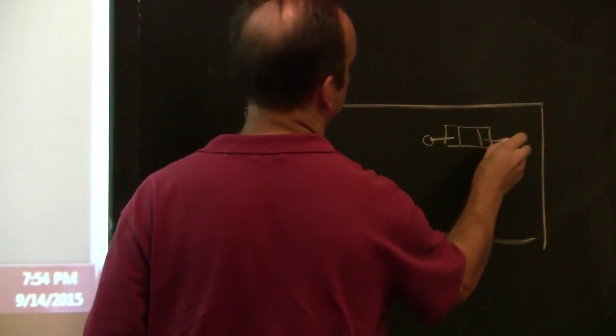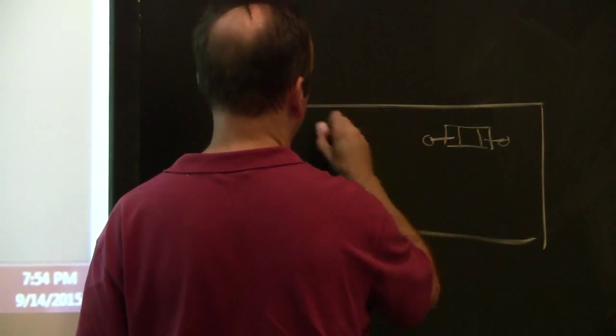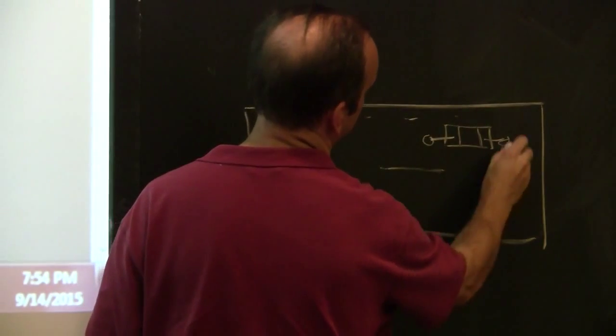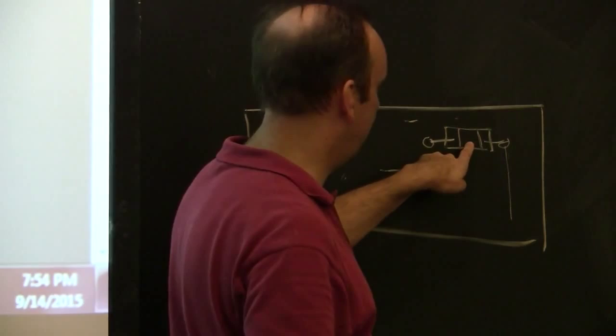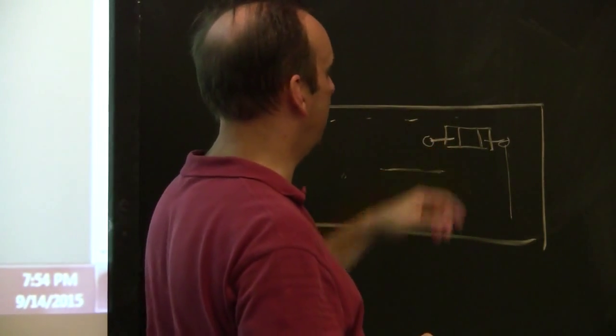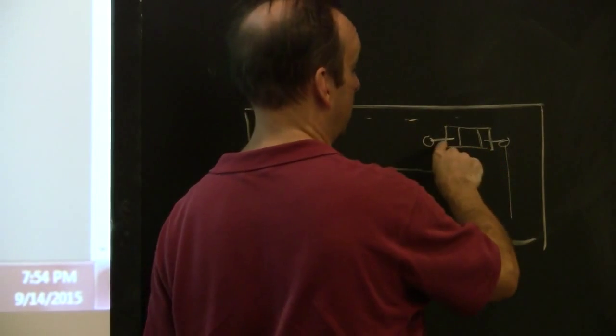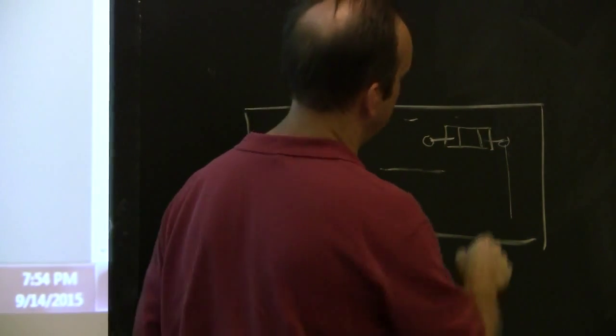There are probably vias here. The vias, depending on what the capacitor is doing, may be tied to reference layers that are inside the board. They may go off somewhere else to a signal. The point is that this capacitor, as soon as you use it, becomes more than just a capacitor because there are parasitics. There's inductance in the leads. There is capacitance.